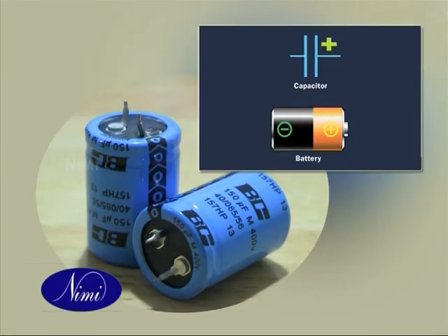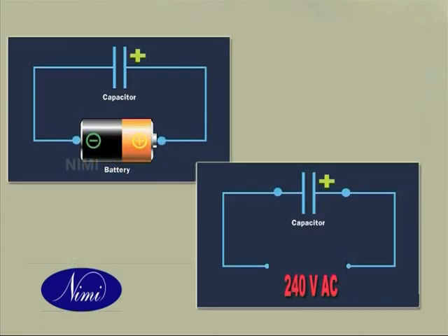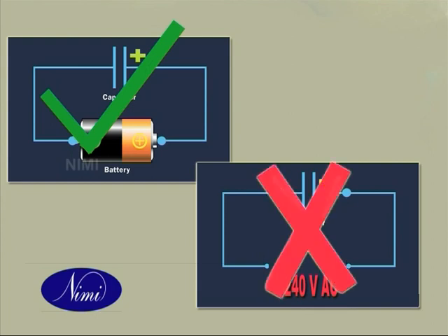One particular point you must always remember about electrolytic capacitors is that one end is positive and the other end negative. Since an electrolytic capacitor is polarized, the positive plate must always be connected to the positive side of a circuit. Be very careful to make the correct connection, and to install the capacitor only in DC, not in AC.